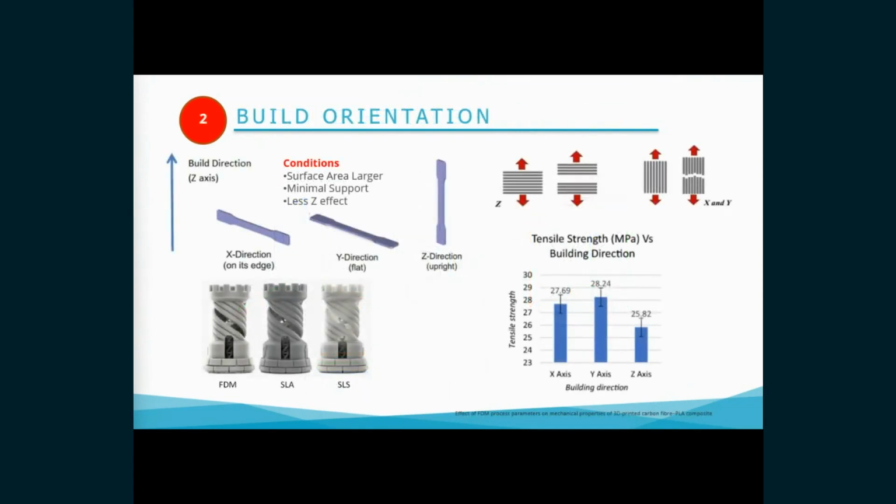One of these important factors is part orientation, which is also called build orientation. How you orient your part in the printer will play a significant role in delivering the final quality you want from the additive component. By orienting the part in different directions, there is a significant difference in the print quality.